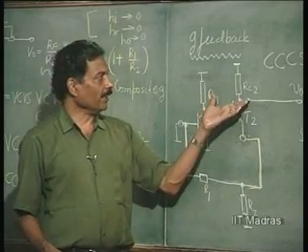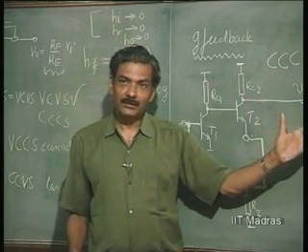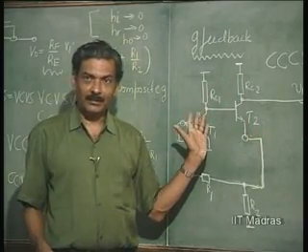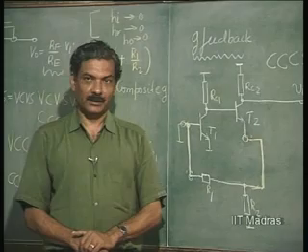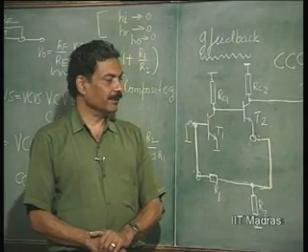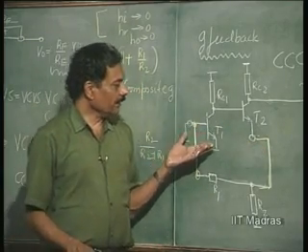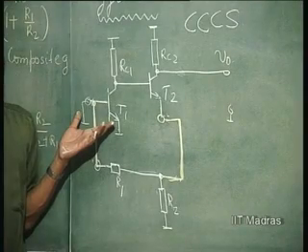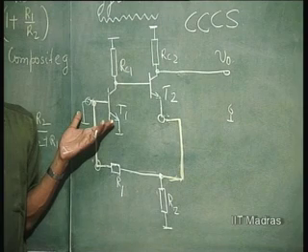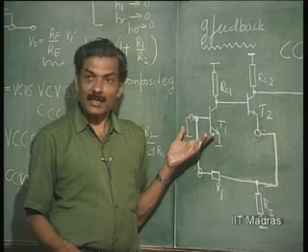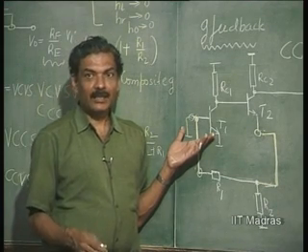This pair gives you problems if the loop gain is pretty high. But if you add one more stage of amplifier, make it a triple instead of a pair, then definitely it is rare that such a circuit straight away works without what is called frequency compensation. Right. We will discuss these effects of high frequency and effect of delay in the individual stages at a later point. That is also very important. So, we always restrict our operation if possible to 2 stages. When we go to 3 stages, we encounter several problems, okay, in the operation of the amplifier satisfactorily. So, overall feedback is mainly restricted to 2 stages, right. Under rare cases one can go to 3 stages, but then there will be bound to be problems.